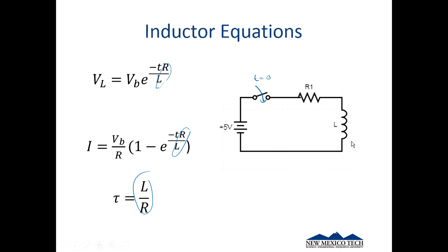And just a little design note, both on capacitors and inductors. If you have to design a circuit or some time constant, there's lots and lots of values of resistors and significantly fewer possible values of inductors and capacitors. So design around your inductor or capacitor first, and then you can fill in with resistances later.